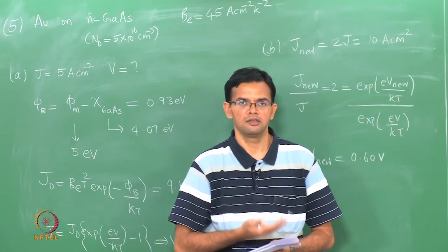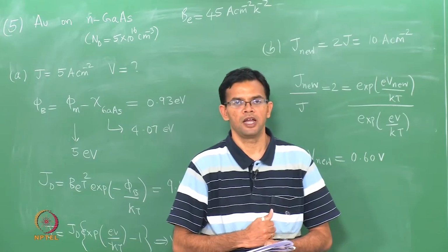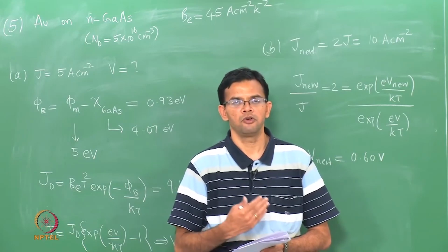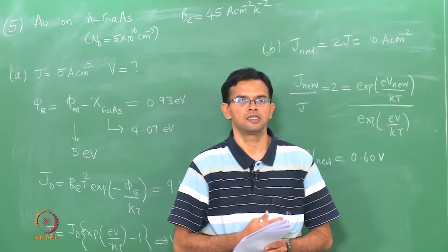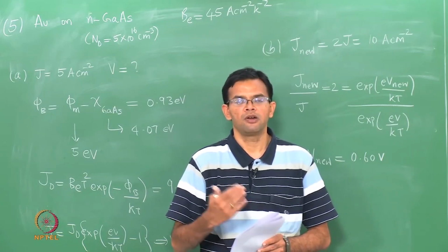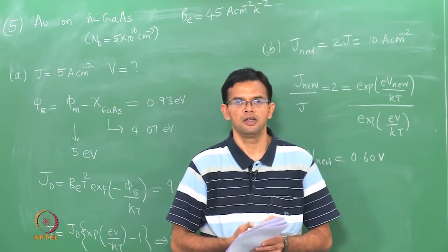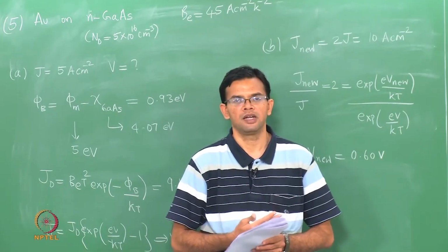So, in the case of a Schottky junction, which is essentially a rectifier, we have seen how to calculate the Schottky barrier voltage, the built-in potential, and also the current during both forward and reverse bias. An ohmic contact is much simpler. An ohmic contact is essentially a resistor, and the resistivity is usually given by the resistivity of the semiconductor material.